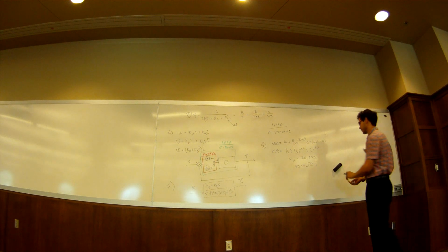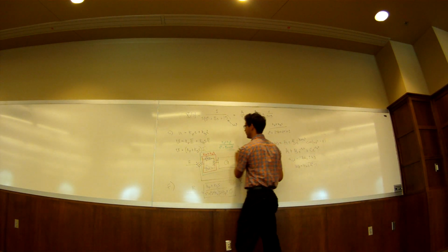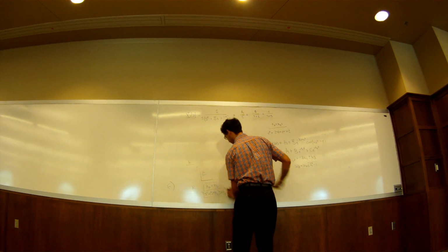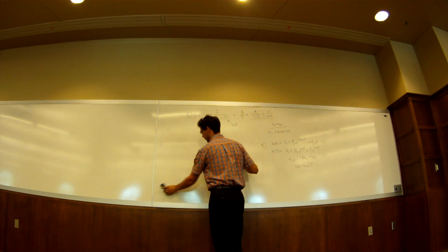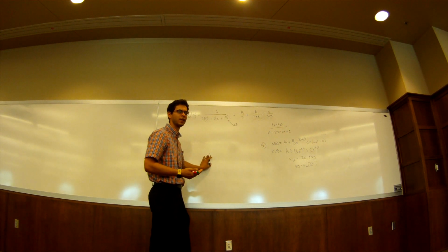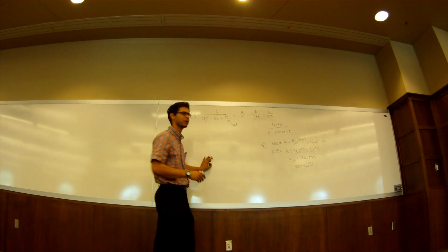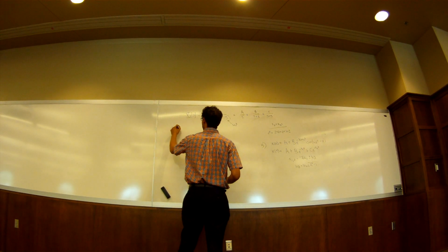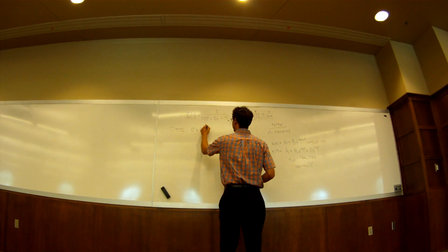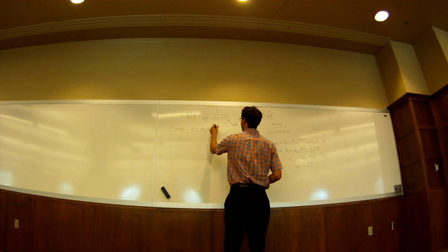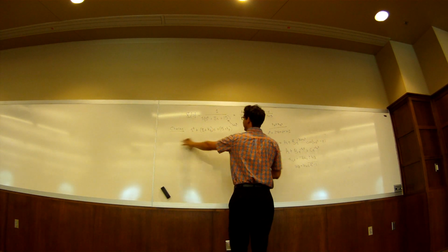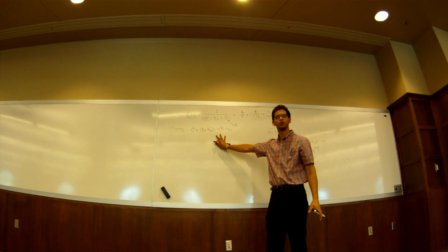All right, let's move on to part H. I don't have the proportional control now. For root locus, the only thing that matters is your characteristic equation. The numerator doesn't matter. So my characteristic equation is s squared plus (8 plus KD) s plus (15 plus KP). This is the only thing that matters. This is going to draw your root locus.